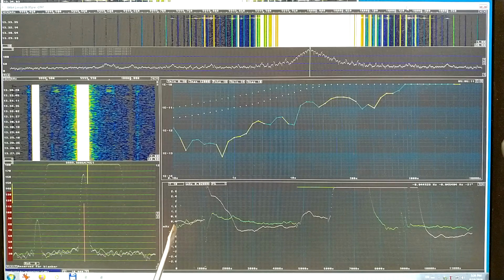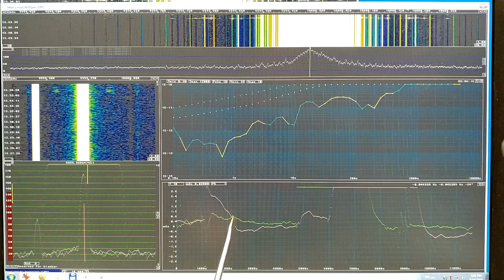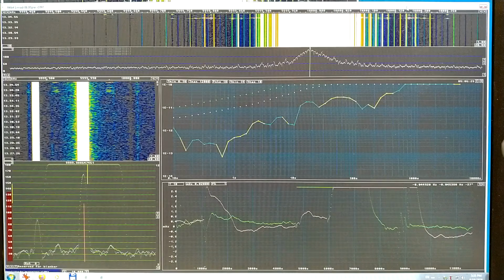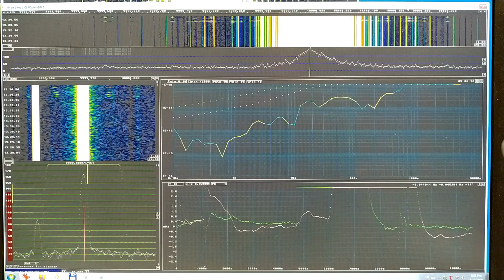Here is the original frequency versus time. You see how the noise looks. This is where I swapped the filters. And here I have cleaned the filters. I have not really waited long enough, but it looks even better than here. So to me this is a new phenomenon. I would call it thermoelectric noise in dirty connectors.